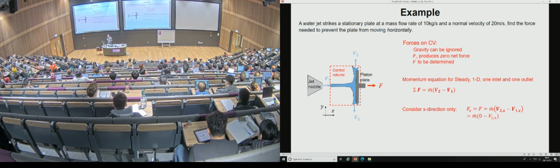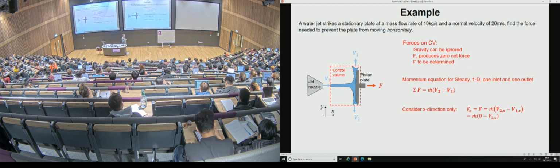The force is equal to the change in momentum flux coming in and coming out. Or the other way around, out minus in. It doesn't really matter as long as they're of opposite sign. And you will see in some of the questions, different coordinate systems are used. The essential is that you're looking at the difference between the momentum flux.